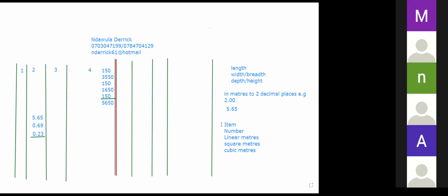Okay, so we have an item. How do I deal with an item here? I come in my dimension column, I write an item as or square meters or whatever. So we call that an item. Take, for example, clearance of site, removing shrubs, removing small trees, grass and everything.